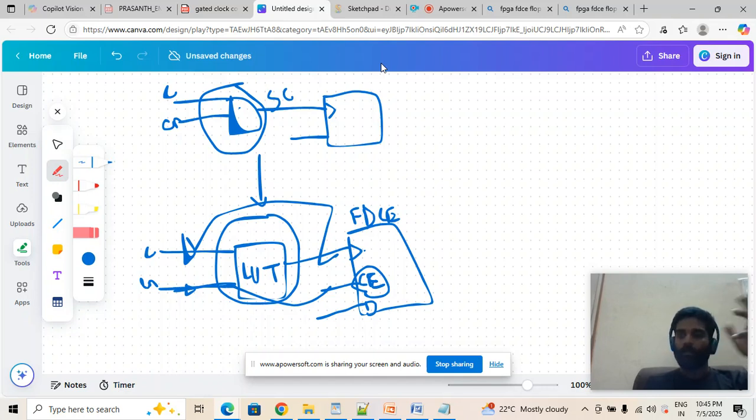For example, we can try writing some constraints, like the XDC constraint. You're all aware of constraints, right? We need constraints on an FPGA platform, for example IO constraints or clock constraints. We'll provide all the constraints, and then we can go for some attributes. What do these attributes do?